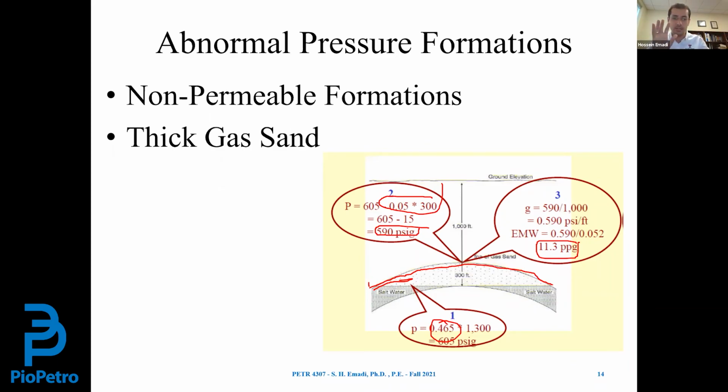Basically, to answer the question, it depends on these factors: how deep we're drilling, the amount of underbalance, the property of the formation, how permeable the formation is, and also the property of the formation fluid, how viscous or how light it is, whether it's oil or gas, stuff like that. Did I answer the question? Is it clear for the student who asked the question?